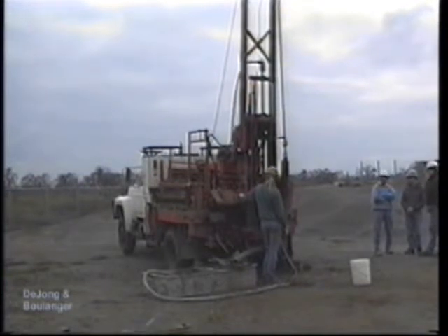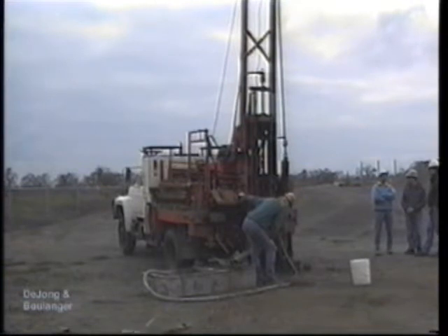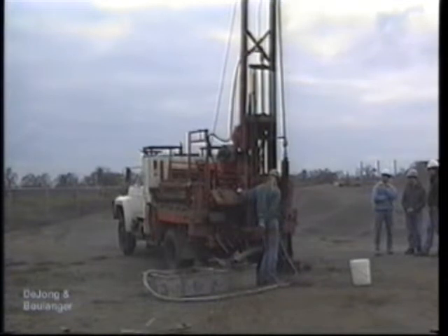Failure to distinguish between natural and drilling-induced fractures on the drilling logs can lead to a completely erroneous interpretation of a rock mass's characteristics. Alteration to the drilling equipment and procedures can significantly improve the core quality and percent recovery in many situations, and these changes should be recorded on the drilling logs.